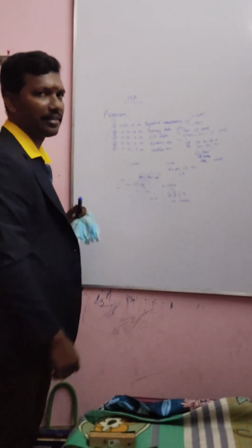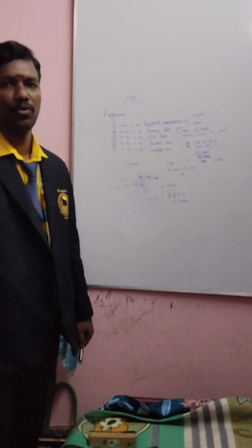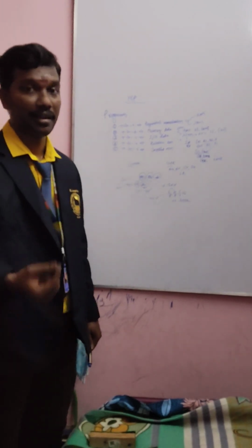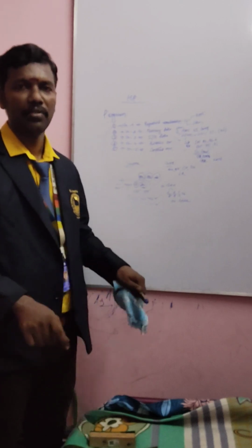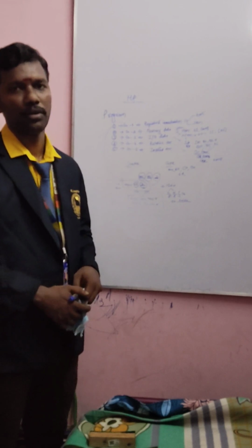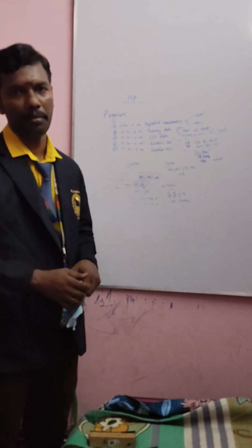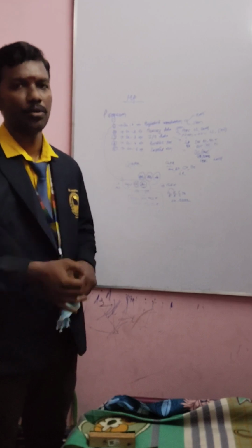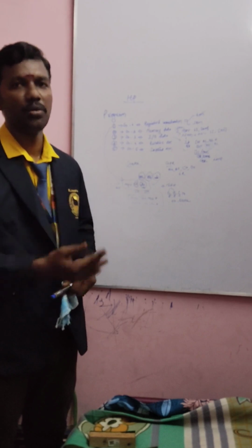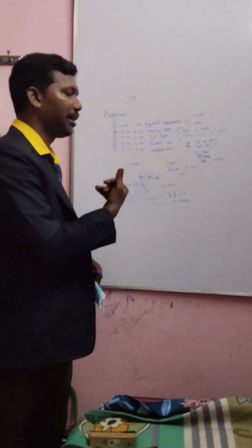Next come to the implied addressing mode. What is implied? Generally we call it implied since, as the name itself says, in those instructions there is no representation of operand and output. So only the operator will be there. The operator itself can define what it is going to do. That means processor control instructions come under the implied addressing mode.